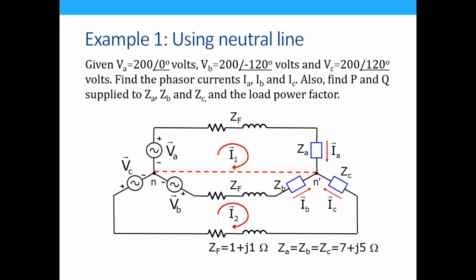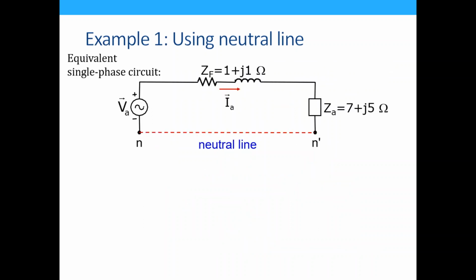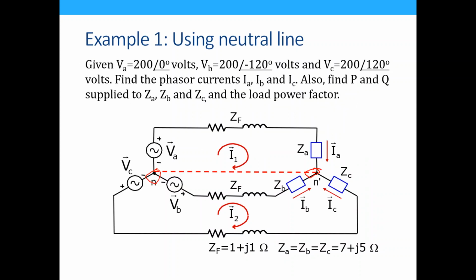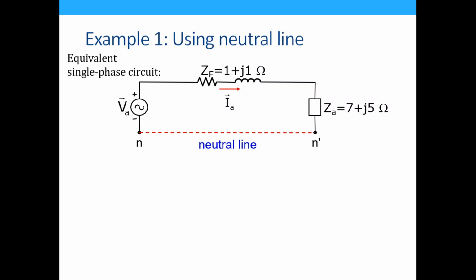So we have an imaginary line connecting the 2 points where the balanced three-phase system converge to each other. Okay, and we get a neutral line. We just analyze the circuit as compared to this circuit, which you need a mesh analysis to solve. This circuit is actually much easier because you'll just be solving it using voltage division. It's just a single loop, single KVL, etc., etc.